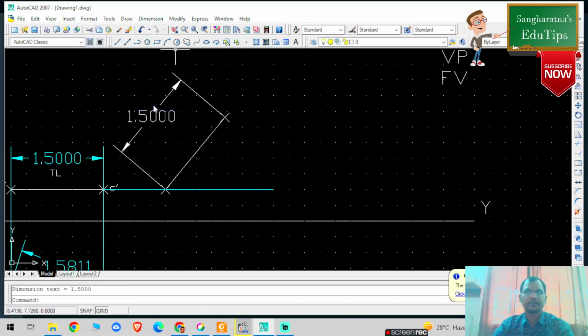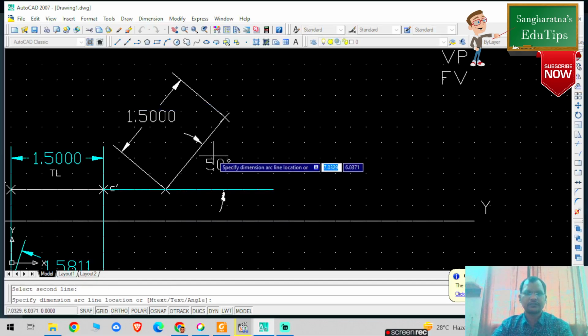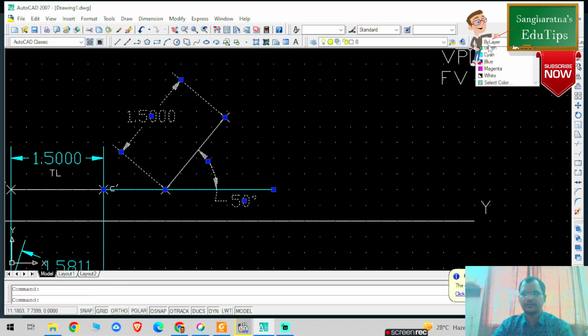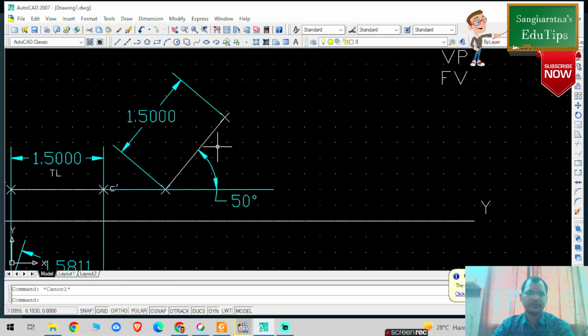Go to dimension, select angular, okay. This is one line, this is the second line, right? So this is basically 50 degrees, right? Convert this particular dimension into cyan color. Press escape, okay. Now you can give the naming. Go to the text, select any point on the screen, specify height. Here I am using 0.1 and rotation angle is 0. So this particular point is my A dash, B dash, and this particular point is my C dash, okay. And this is basically the true length inclination, okay.